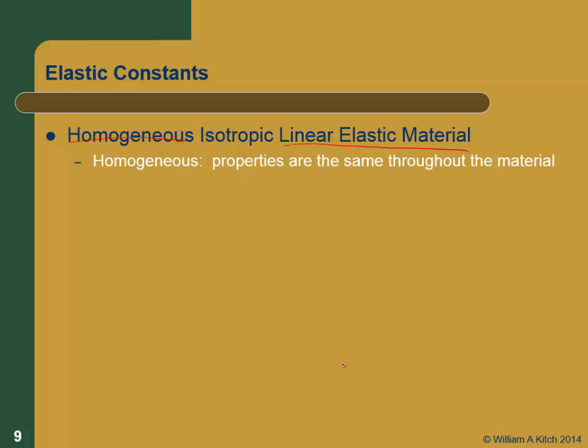Does that mean it's a uniform material? No. Think of these composites you have right now, where you see these composite sheets where you've got basically layers of either carbon fiber or fiberglass or something in a matrix, but the sheets are all laid out. So every point I go in there, it's the same material, right? In a macro sense, it's the same material. I've got this material that's got carbon fibers in these directions, and it's in a matrix, and it's the same everywhere, but it's not the same in the X and Y directions as it is in the Z direction, because one of them is a bunch of layers where the fibers run this way, and the other one goes across the fibers. It's not the same in every direction.